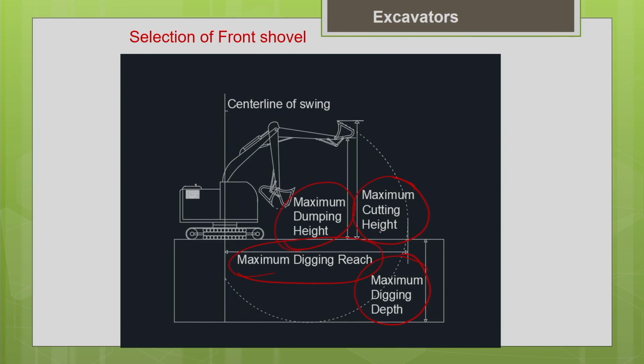You completely stretch your boom or the arm, so that you will get the maximum digging reach possible with this machine. It depends upon the dimension of the boom, and you can get this data from the manufacturer. It will help you to know what is the maximum working radius possible with this particular machine. Based upon that you can make the selection.